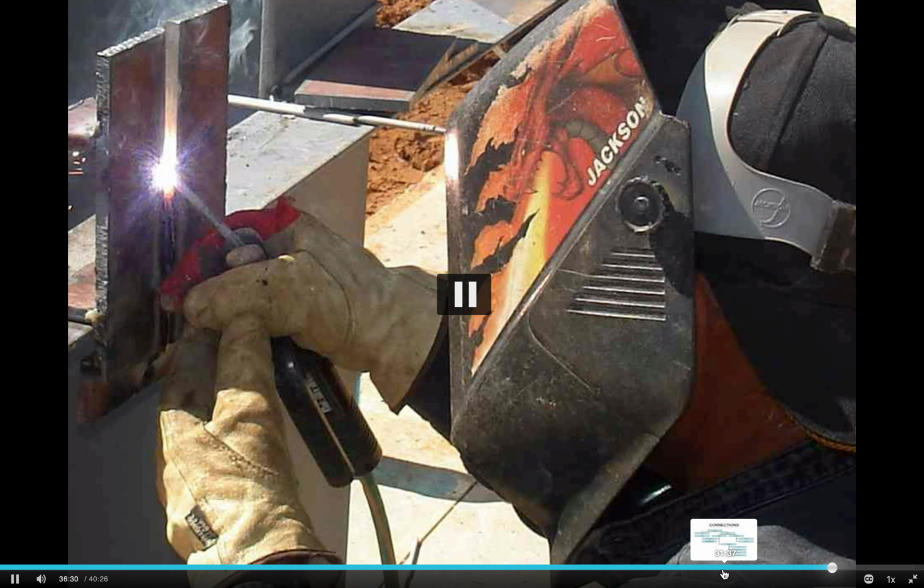Obviously, with the heat and the electricity comes the light. Never look directly into a welding light. It's like never looking into an eclipse. You've got to have the proper personal protective equipment, and not only are those the welding gloves, but there's a shield and a visor. Underneath that visor there's probably shades as well, and then you want to have protective clothing on you so that any of the splatter doesn't get on your skin, because it'll burn.